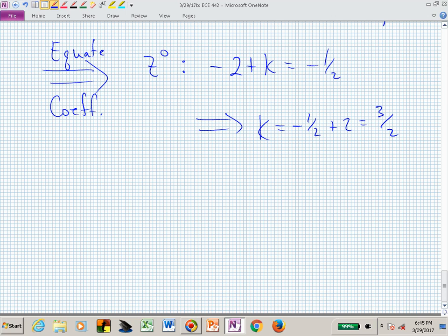And if we now cranked up the gain from 0 up to 3/2, we would end up with a desired closed-loop transfer function having a denominator of z minus 1/2, and the numerator was k. And what do we know about the closed-loop system in terms of behavior? Is it stable or unstable? Where's my closed-loop pole? It's at 1/2.